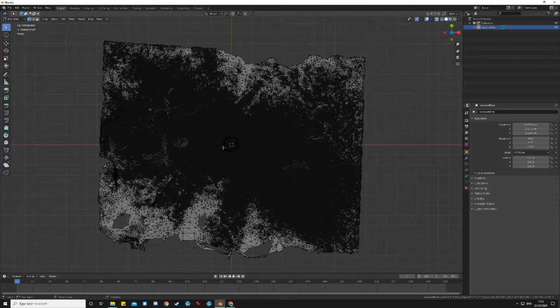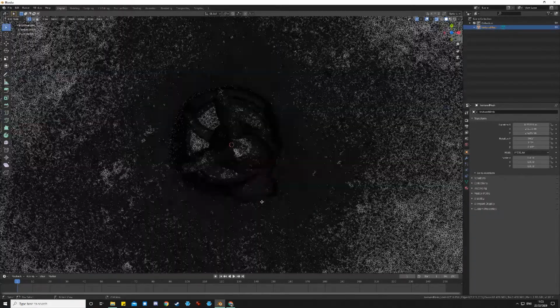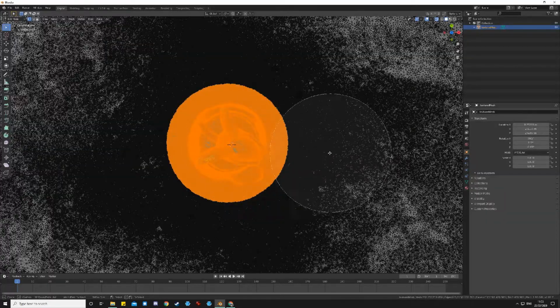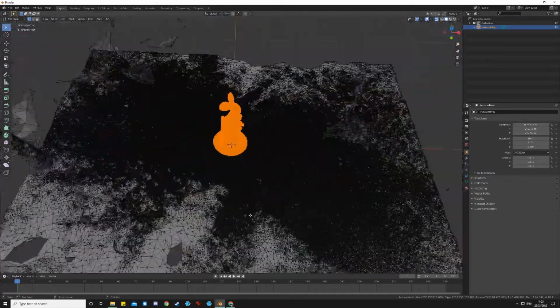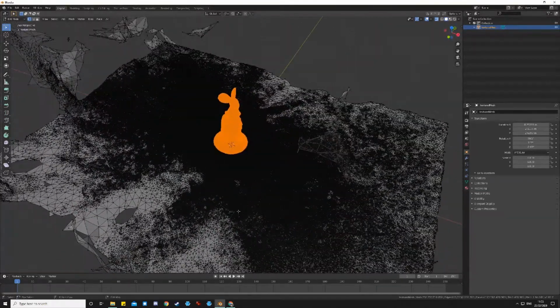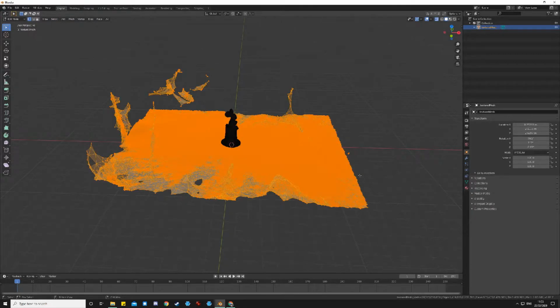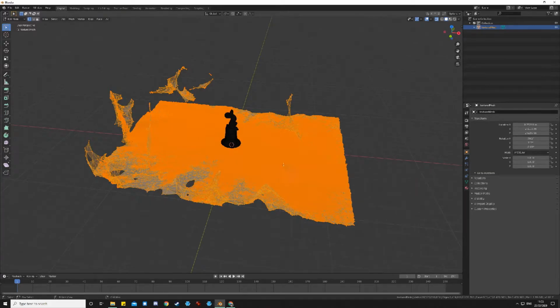Yes, so if I go back to 7, which gives me the nice top-down view, I can see that's my object there. I'm going to press the circle to just encompass the object, and I'm going to press the mouse click to select it. Now that means my mouse is selected, but all this other stuff that I don't want is not selected. So what I want to then do is invert my selection, which means I can press Control I to invert, or I can actually come up here and use Select, and go Invert. Let's just say Control I, and that means everything but the mouse is selected. So then I can press X and delete those vertices.